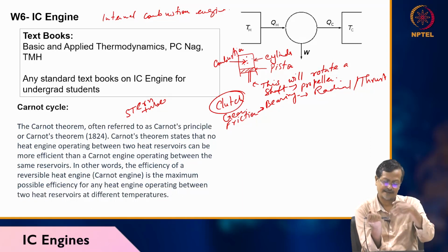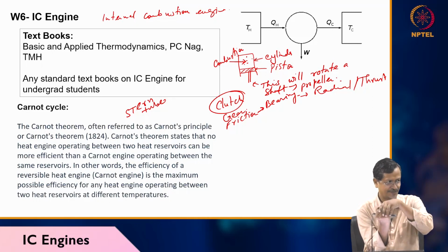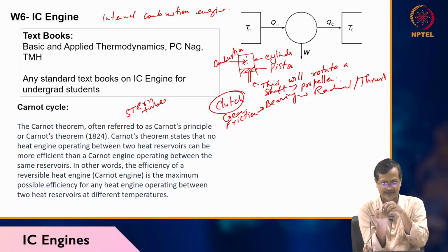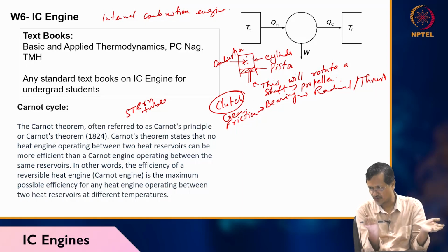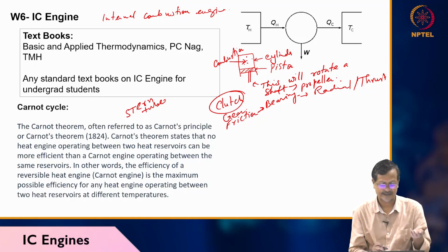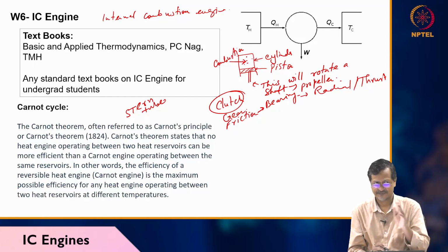So this is my propeller, the shaft is going there, the shaft is going through a seal section, seal and bearing, called the stern tube. This lubricating oil or grease should not go out, so you must seal properly. These days new seal arrangements have come up, water based seals and other types of seals.